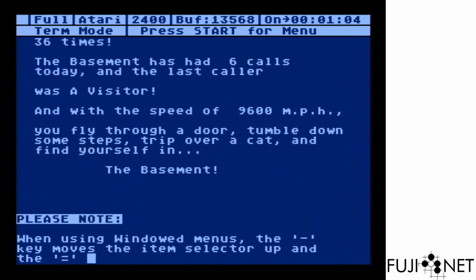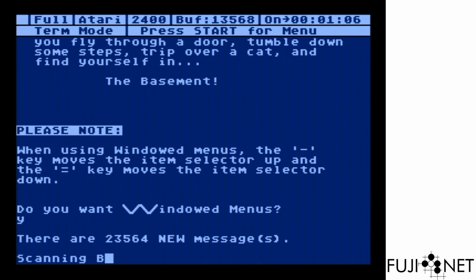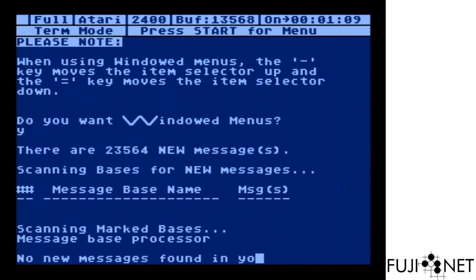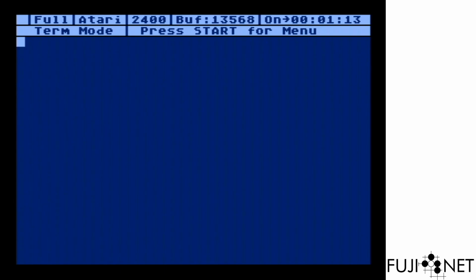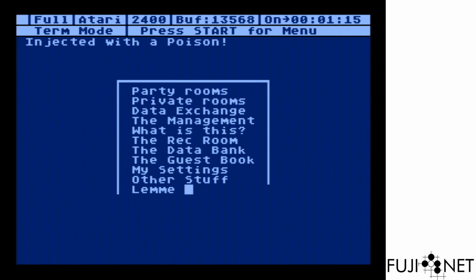The FujiNet itself has a large buffer sitting on it, which allows any network traffic coming in as packets to be buffered and siphoned off at leisure by the Atari. So we don't have to worry so much about what we historically have had to worry about with modem setups, like implementing hardware-based flow control with RTS and CTS signals. All of that's kind of meaningless now.